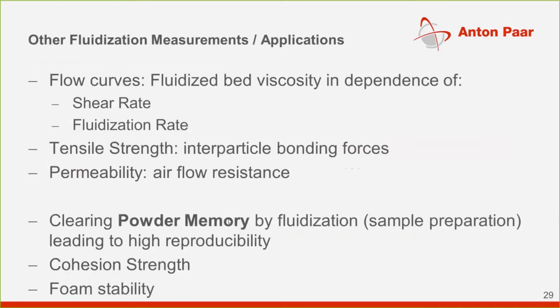There are also other fluidization measurements and applications. So one is flow curves. This will also be discussed in further webinars. Flow curves are basically fluidized bed viscosity, where the apparent powder viscosity is measured in dependence of two factors, the shear rate that is applied and the fluidization rate. So it's measured in fluidized and subfluidized state, for example, with a shear rate variation.